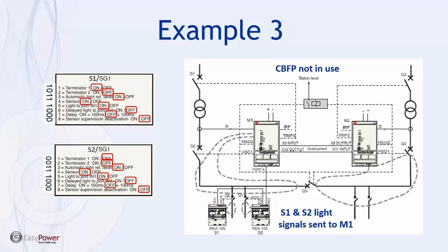So really this would be like for a maximum protection situation. Now let's say that you don't want to keep this switch on, you don't want breaker failure, and this switch is off because it's not a typical application like I just mentioned. Then what's going to happen is you can detect arcing faults, and if you have a breaker failure, then something's got to clear that condition. So if you're not sending light back to the main unit to trip, then you're going to have to rely on the speed of your main overcurrent protection for that. So you are going to have a little bit of incident energy in that situation.